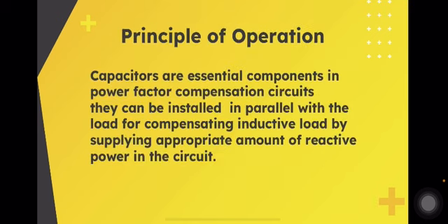What is the principle of operation behind a power capacitor? Capacitors are essentially components in power factor compensation circuits. They can be installed in parallel with the load for compensating inductive load by supplying an appropriate amount of reactive power in the circuit.